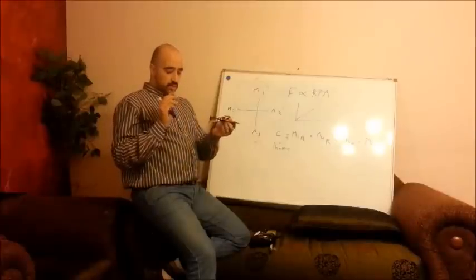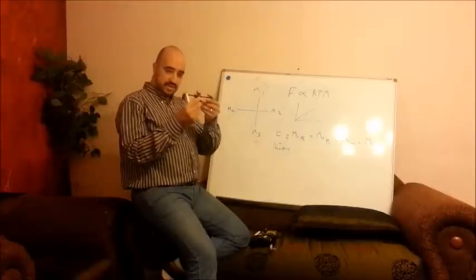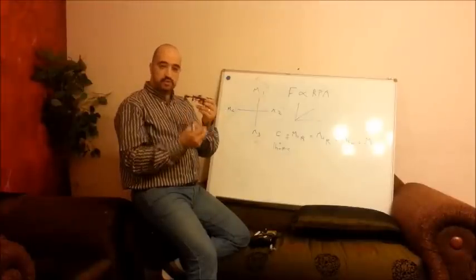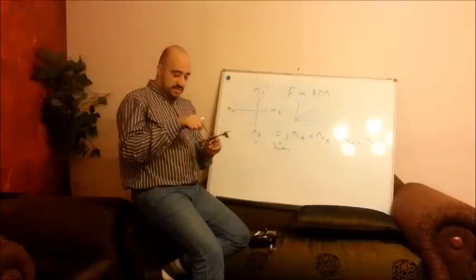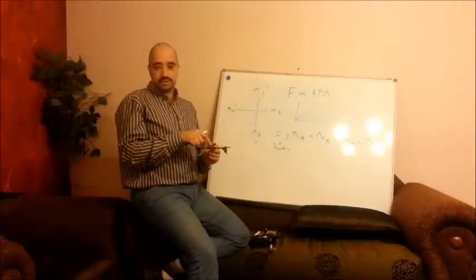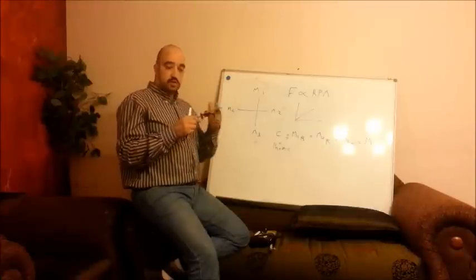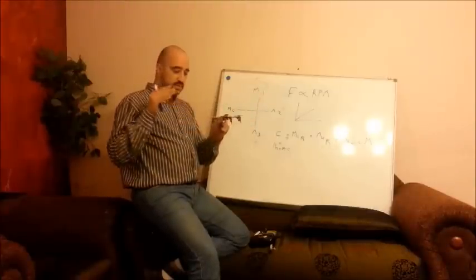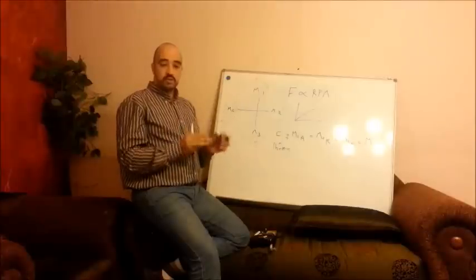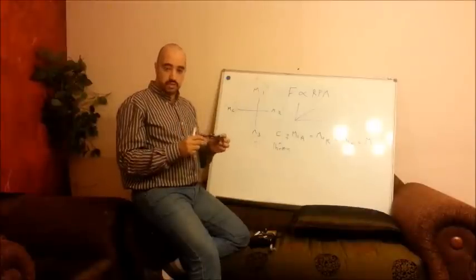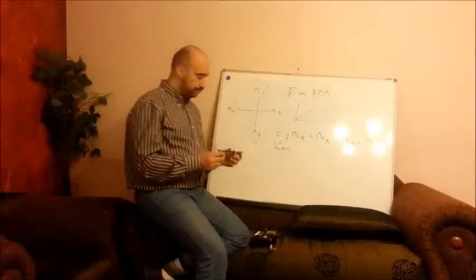You cannot say that this RPM is exactly the same as this RPM and they will produce the same thrust, and the CG is exactly here. You cannot say that, and you cannot even ignore outside effects. Maybe some wind comes from this direction. So without balancing, without using a gyro, without active balancing, the quadcopter will not be able to fly at all.